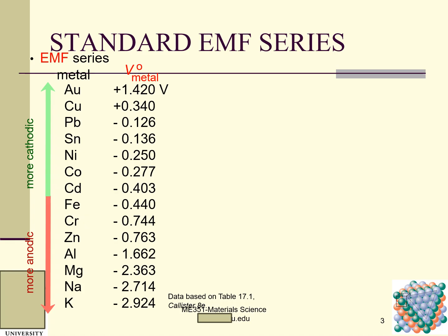When their ions capture these free electrons, they become atoms. So usually these are more cathodic materials, and they result in reduction. Reduction means deposition. You can see more atoms on their electrode. So this is very, very important here.